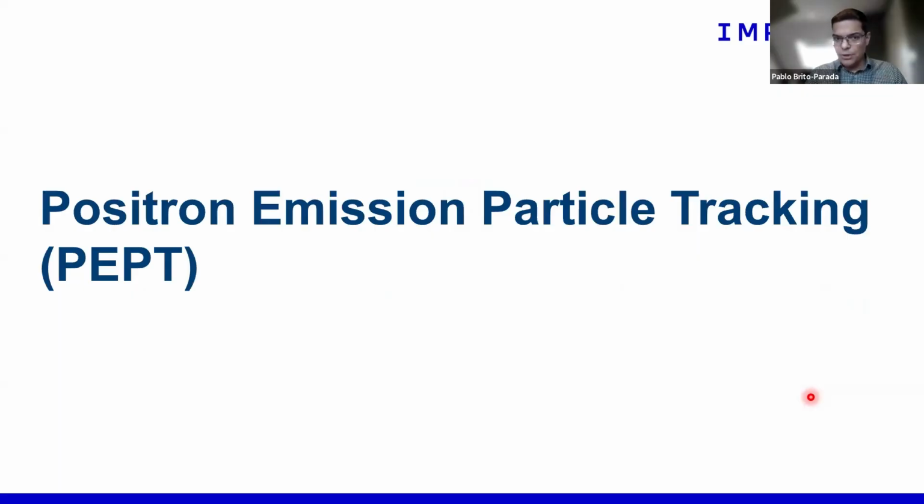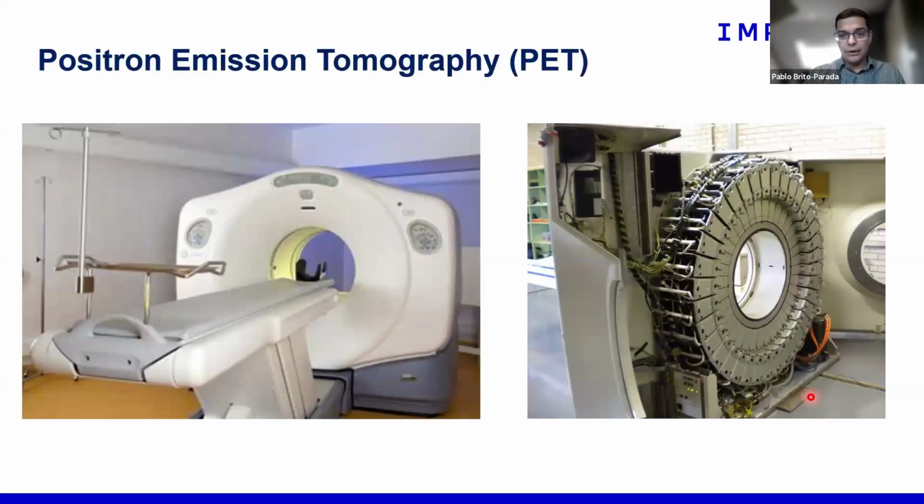So introducing positron emission particle tracking, or PEPT, as a technique that can be used to track particles within a flotation system. So what PEPT allows is exactly that, the visualization of the path that the particles will follow within a system. And those particles for PEPT are radiolabelled tracer particles that the trajectory of which can be measured using a positron emission tomography.